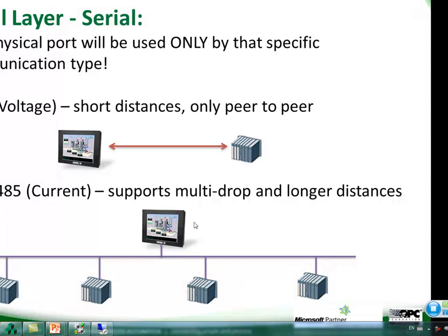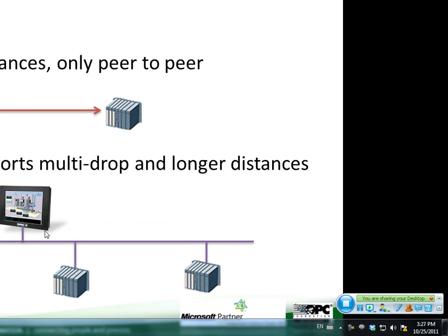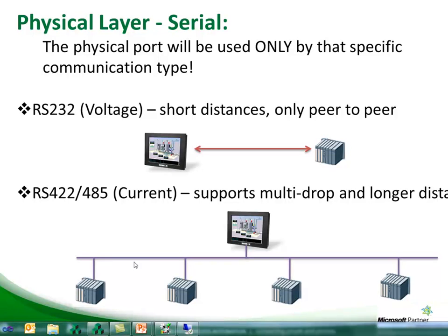So when you have a multi-drop architecture like this one, and at least one of the devices is down, I highly recommend disabling the communication with the one that is down until you figure out what's wrong, because this is going to slow down everything else, because the communication is synchronous. So it goes here, here, and then stops, and then goes here, here, here, then stops here because of the timeout.